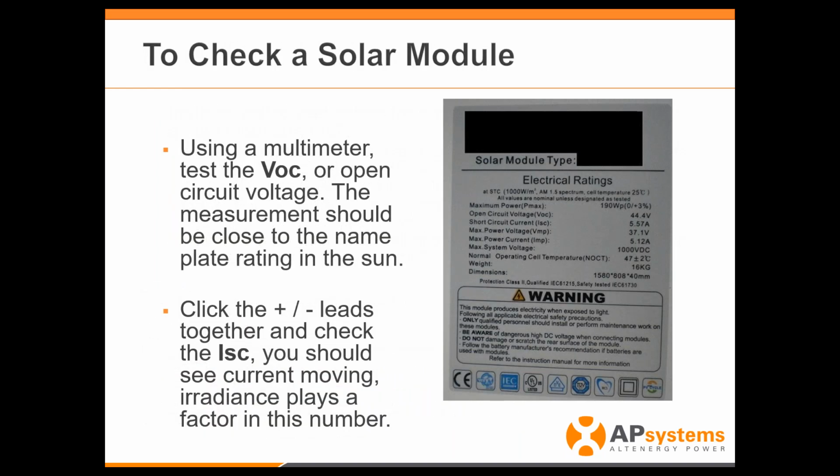One of the things that I did ask him to do when he got on site, just to verify, just to make sure, because I hate to say I'm 100% right every single time. That's not possible. But what I said was, when you get on site, I want you to take a look at the back of the module and say, what is the VOC of the module? Then take out your multimeter and just plug that in and just verify that voltage.